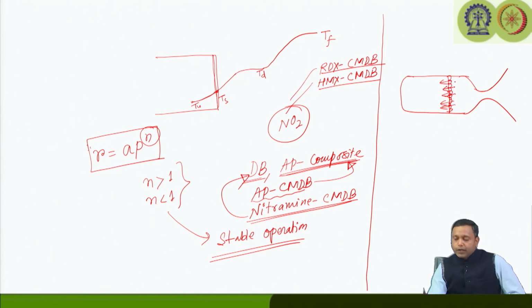Once the propellant is burning, it is going to produce product gases, and those gases are going to expand through the nozzle. By burning of the propellant, it is generating gas, whereas the mass leaving the nozzle is m dot n. If we denote the throat area as At, we may note the burning surface area as Sb. We can denote the chamber pressure as Pc.